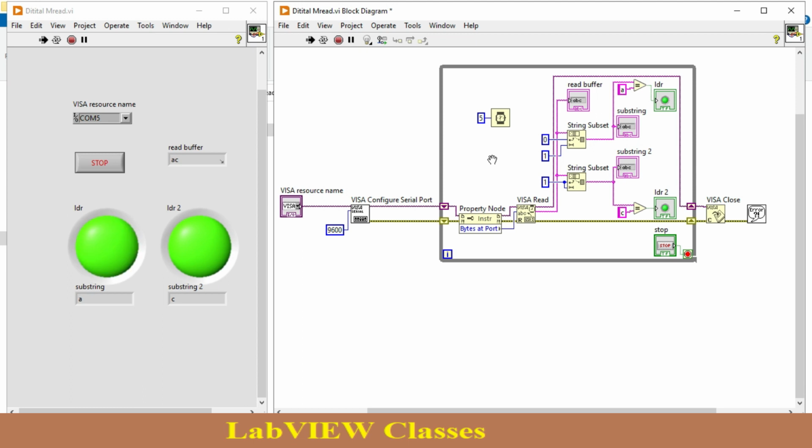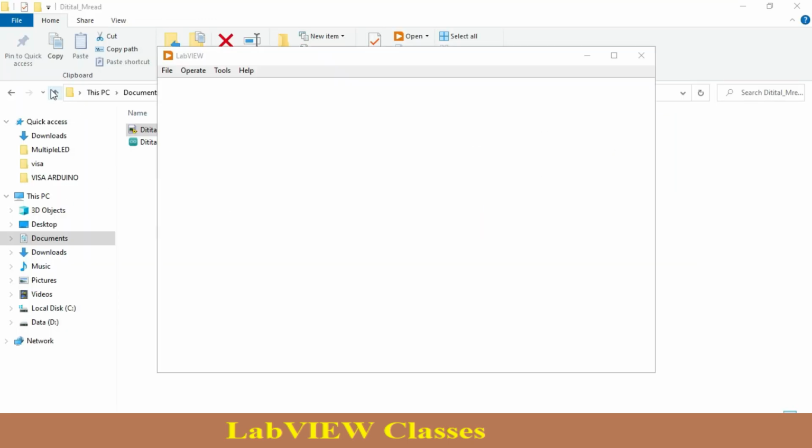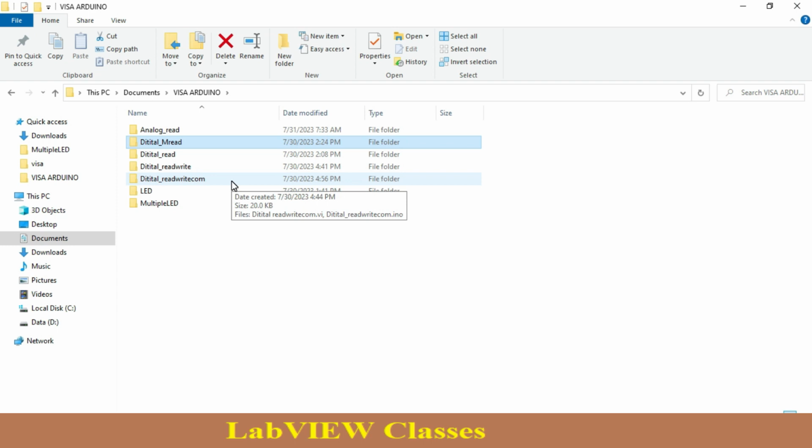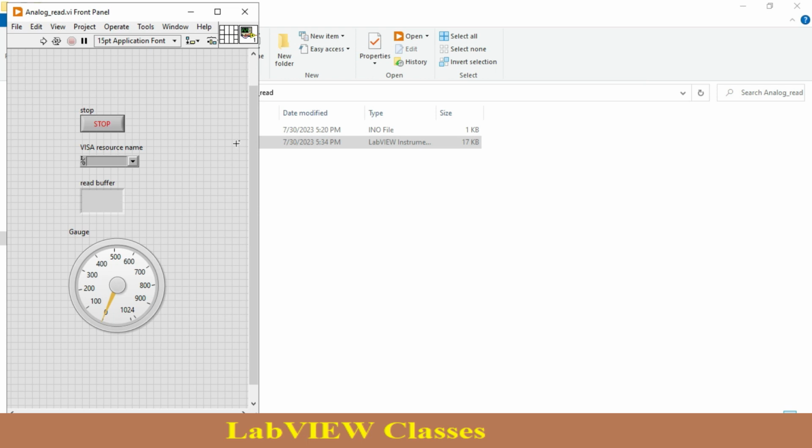Okay. So now I just go with the last case of today, that is analog data read. We just went with digital data till now. Right now I just show you the analog data part, that is my potentiometer or any device, or in your case it will help also, because let's say you just want to check or read the power supply output voltage, you just need to step down it first, because an electronic device only reads up to 5 volt or 10 volt.